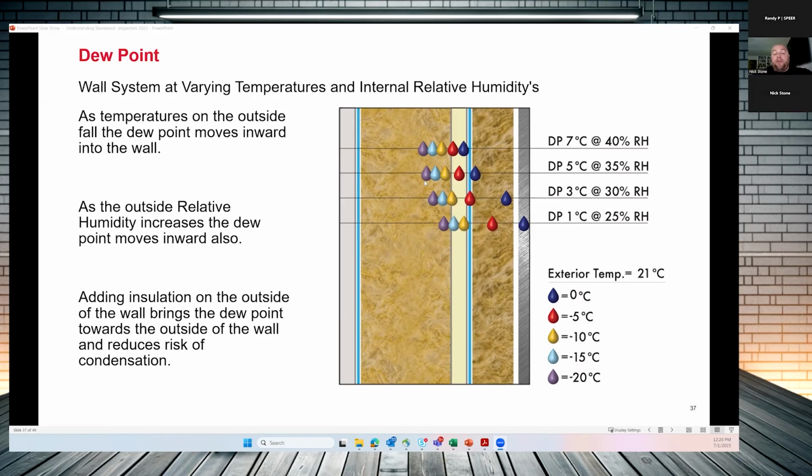Whether it be our framing, our headers, our floor assemblies, or wherever the wood is located, those are going to be weaker locations within that thermal envelope of our walls or our roof line. Now, by adding exterior insulation to the outside of that, we're going to make more and more efficient buildings because now we have consistency of insulation over the insulation and over the frame, which is the really important part of that.